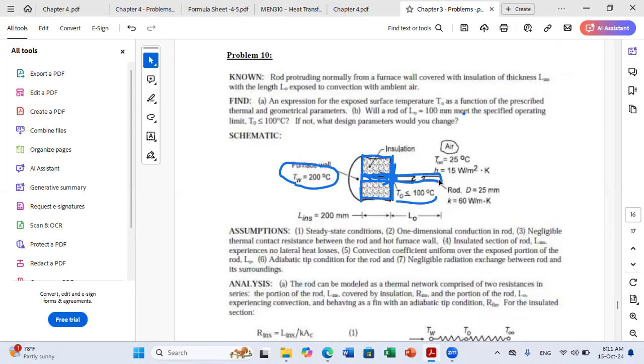It's the one corresponding to 99% of the insulated tip temperature profile; we can consider that this length is enough, because if we increase the length more, the additional heat that will be lost is really negligible. So we will work on these aspects in this problem.